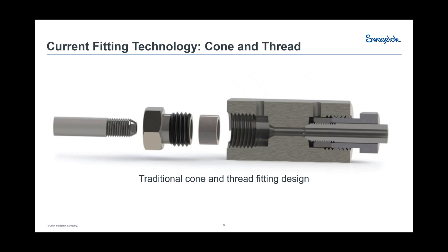The other thing is you end up coining in the surface of that seal. So if you ever try to take it apart and put it back together, you've got to rematch right where it had coined in the first place, all the hills and valleys, which they usually don't. That's why when these leak, people go and nip them up. They pull them up tighter, and they're basically reseating the whole fitting every time they do that.